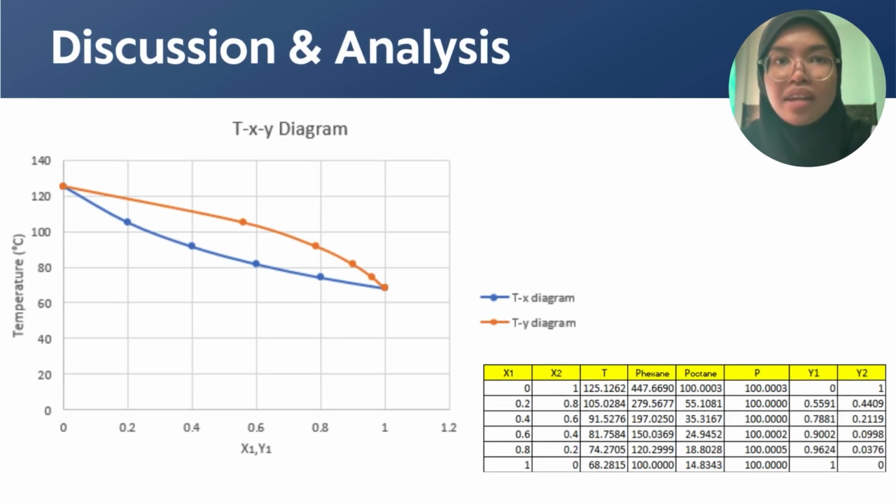Now, let's look at the TXY diagram. In this graph, temperature is on the y-axis and again, mole fraction of hexane is on the x-axis. Since our system is at 87.8 degrees C, we draw a horizontal line at that temperature. Just like before, this line intersects the liquid line Tx and the vapor line Ty. At this temperature, we are also in the two-phase region, which means the system contains both liquid and vapor in equilibrium. From the graph, we can observe the same behavior. The liquid phase is rich in octane and the vapor phase is rich in hexane.